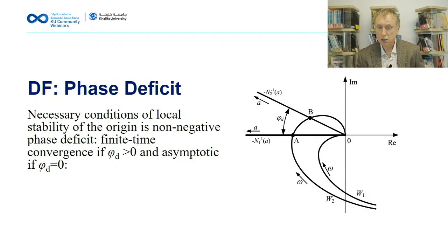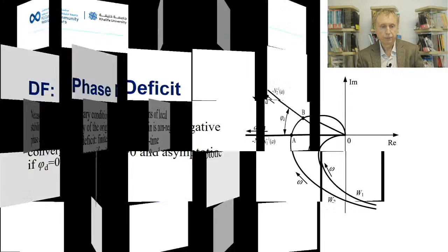In this case, we will have finite frequency oscillations or chattering in the sliding mode control system, and respectively the origin in the state space will not be stable at all. So we have oscillations in the vicinity of the origin and not the stability of the origin itself.